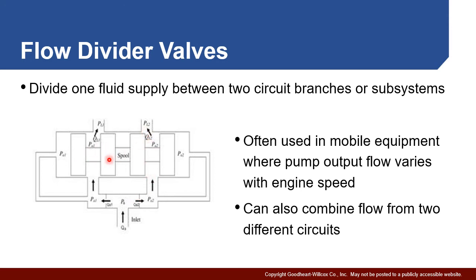And in addition, this is a simplified diagram. We would have a spring to bias this, etc., just to keep it in its center position. The whole idea of this is when we're trying to get the same function out of both of these. You can also modify this. We'll see a few more modifications to it. Keep in mind, we can also use this for connecting two flows. We want the same amount of fluid to come out of both ones. So this can be operated in this direction to divide the flow. It can also be designed to proportionally combine flows.